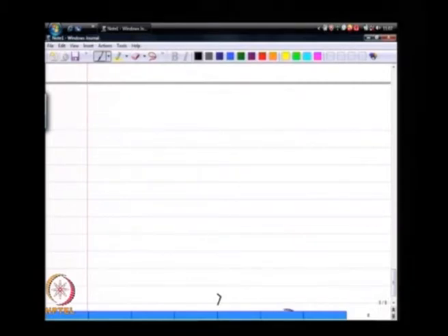So, for that we are going to use the idea that we have a free vortex inside the swirl chamber. A free vortex has a 1 over r dependence of the swirl velocity with the radial coordinate.